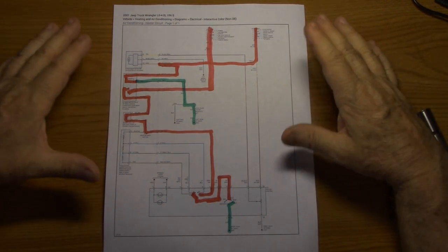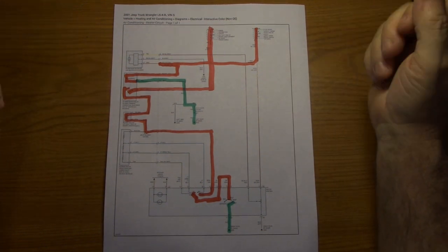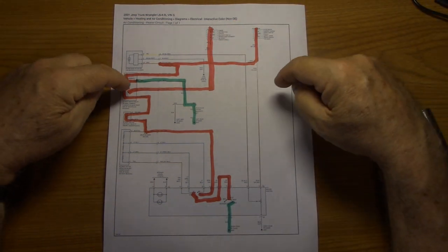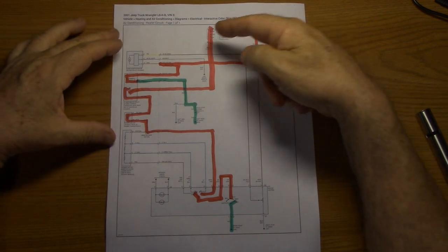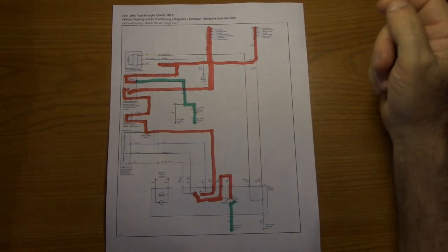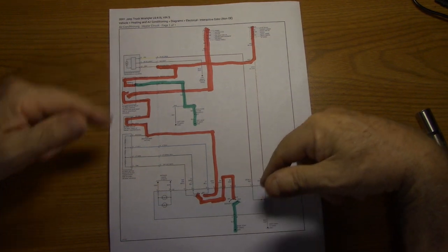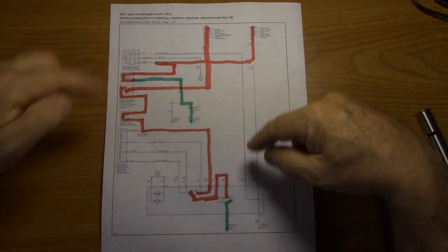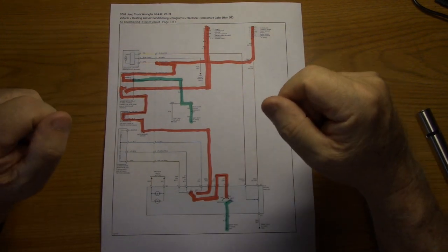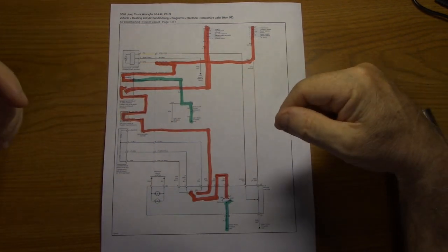All right, so I printed out from ALLDATA the wiring diagram for the blower motor circuit. Actually there are two circuits. One circuit is for the blower motor relay, and the other circuit is how the blower motor gets power. So there are two circuits. All right, and so you break it down. Anything that I do not have highlighted here, I'm not concerned about. There is nothing in this area that is not highlighted that can keep this blower motor from operating. The problem is somewhere in where I have it highlighted.